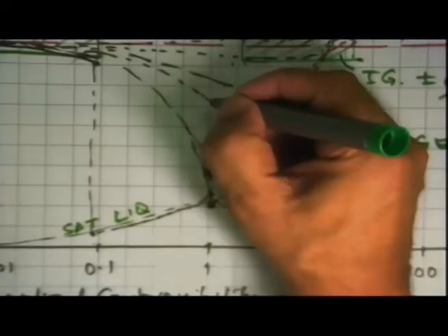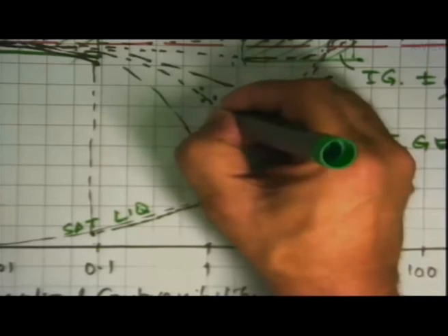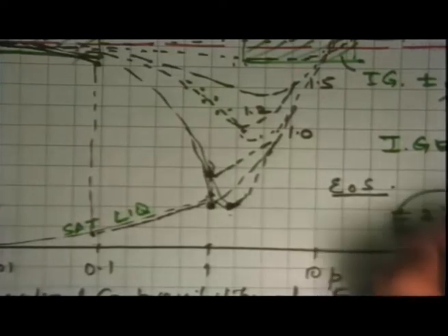And fortunately, what that does for us is that you get a very nice single compressibility chart for all materials. It's not that everything is lying exactly on this line. There is a variability around this from substance to substance, and you are looking at plus minus 2% type of variability in making the generalized compressibility chart in the first instance.